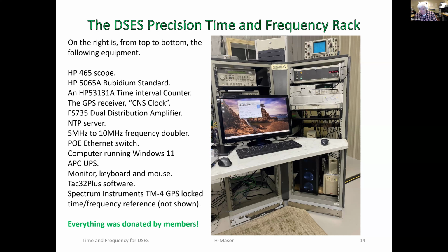Good, because I found that the UPS that was in the trailer that we used to just leave on was very noisy. It was a source of noise, so I just turned it off. This one is pure sine wave. We need to make sure that every UPS we put in at Hasbro is pure sine wave, no cheap UPSs. Great, thanks.